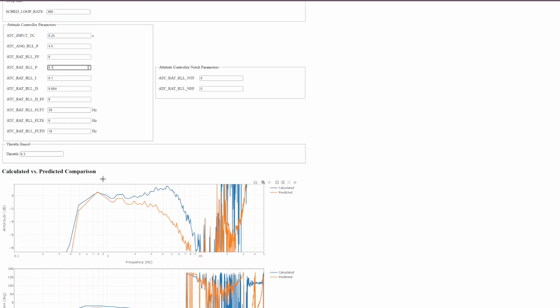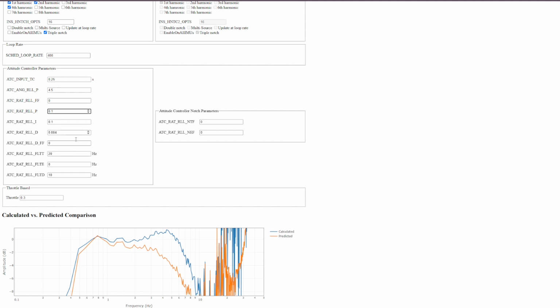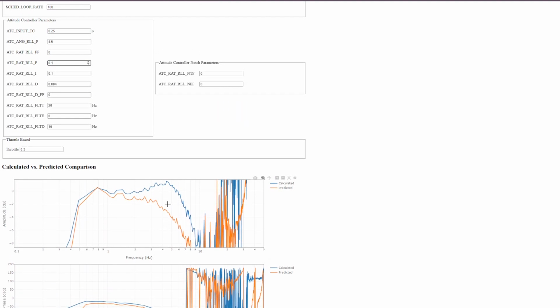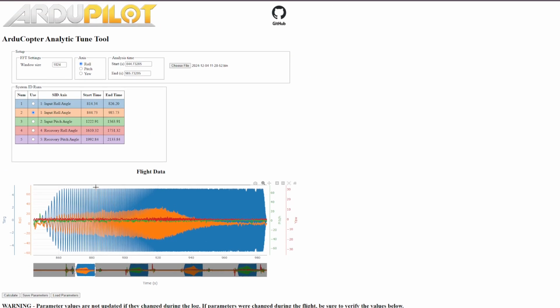If you'd run auto tune, you might be closer to your perfect tune, or you might be slightly over tuned. But either way, you can actually back this off below your tune to go through this process just as I've done here. So the first thing I do is not to actually start tuning this. It's actually to look for saturation. Like all of our tuning mechanisms, the maths assumes a linear system. So it's really important to avoid saturation and non-linearities.